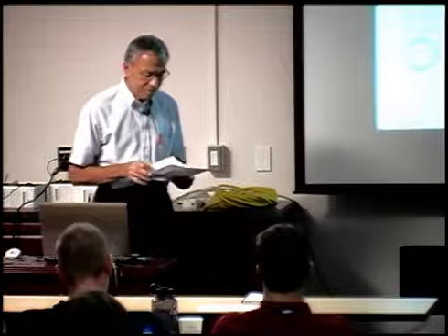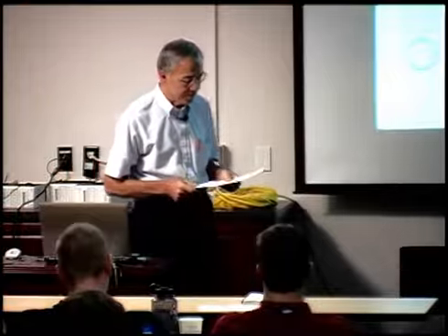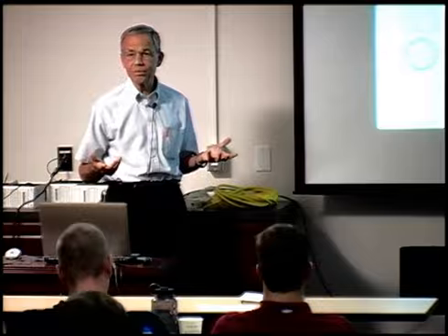In this very small sample, and not the final work, it looked like if you're not driving to rock, it's maybe 10% at most. There's some variation in there, but there's likely to be some difference. You can go back to what our equivalent allowable stress factor would have been, which was 0.725 versus 0.65, 0.6, or 0.55, and you can see that that's probably going to lengthen the piles.